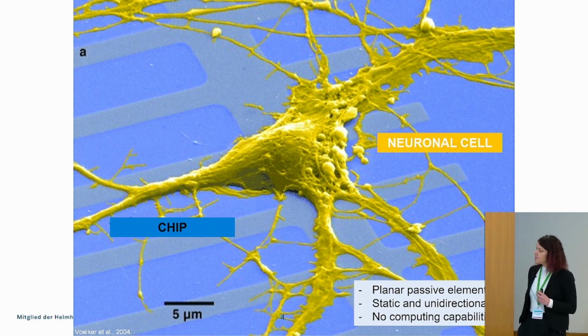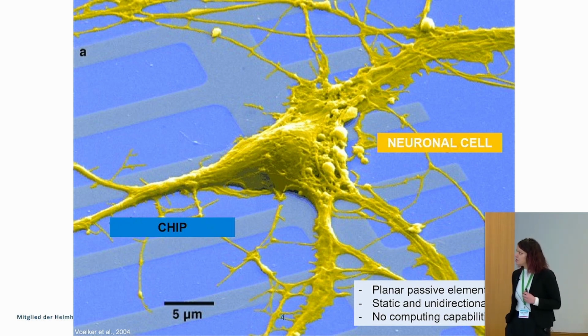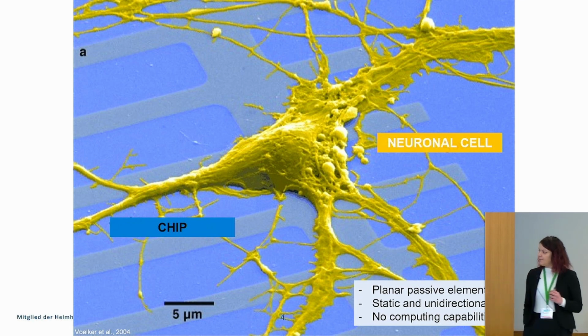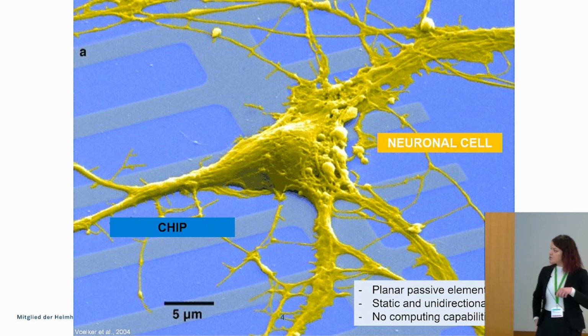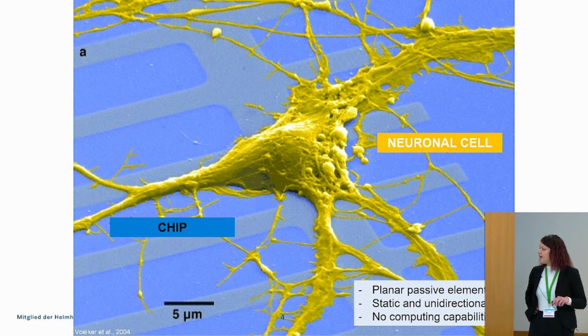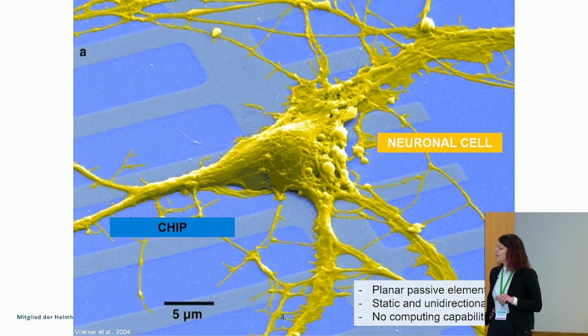So in our case, we focus on using conductive polymers, in particular PEDOT:PSS, integrated as a channel of an organic electrochemical transistor. So this is the typical structure. This is a 3-terminal device with a source and a drain and a PEDOT:PSS channel between the two. And then in this configuration, we have a gate electrode in contact with the electrolyte, which also connects on the other side to the conductive polymer channel.